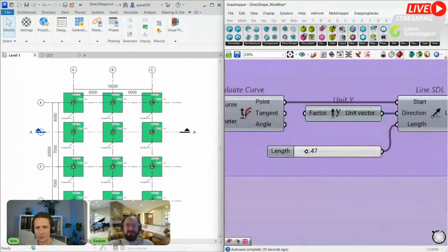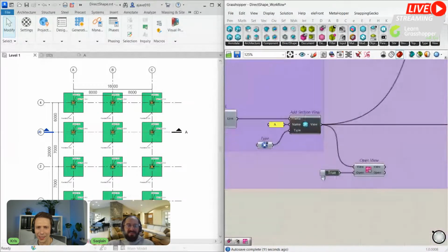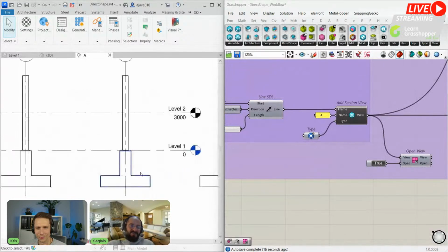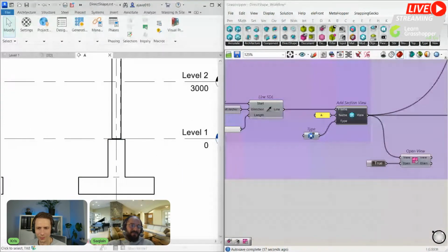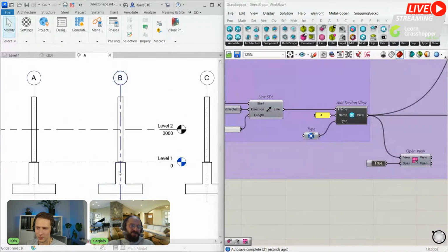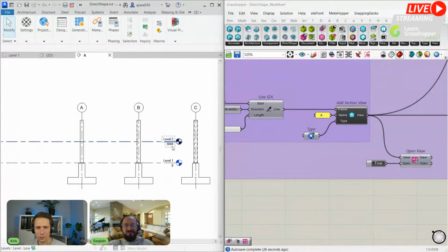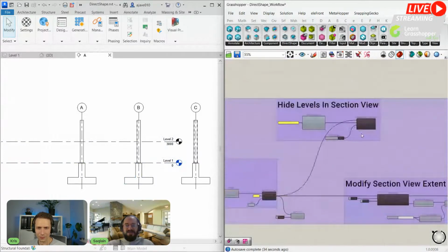And then I also have the freedom to change the scope of this section. So this doesn't need to be very small or wide, it's up to you. And then if we go to the section, what I have explained earlier, we have this problem, it's hollow, as this one is not the actual Revit object, so you won't see the hatch patterns here. And then again, when you create a new section, by default, Revit gives you some objects or some grid lines or the levels you have created here. You can also hide this one here.